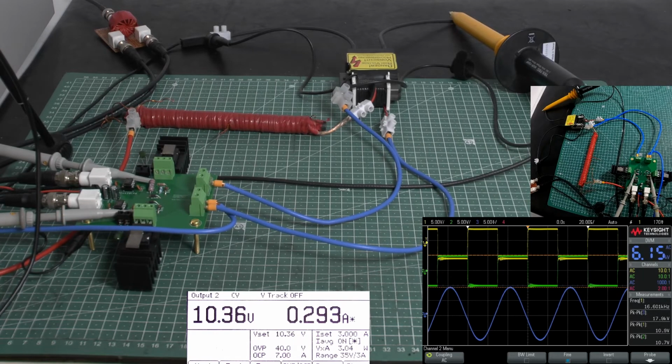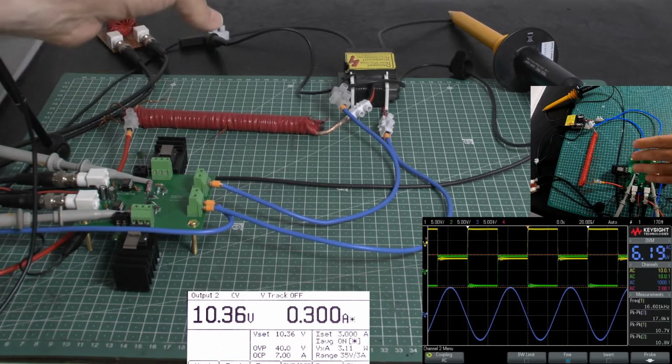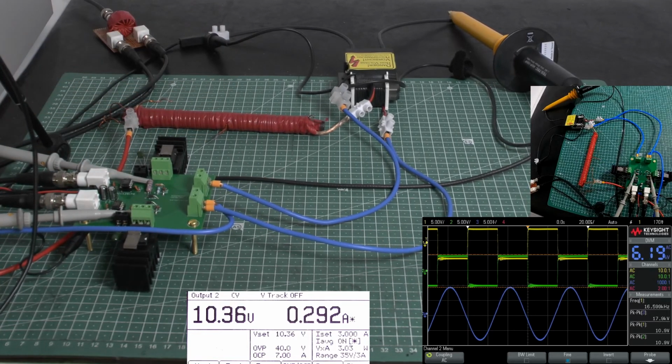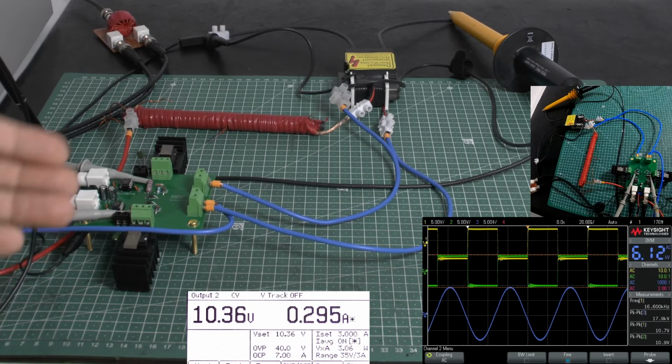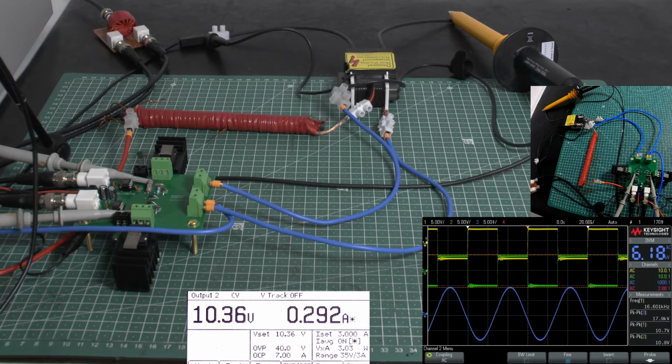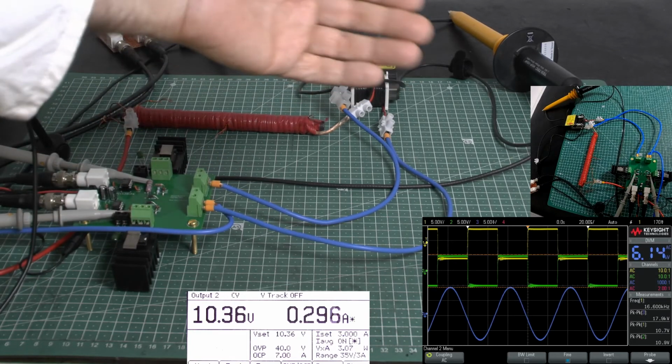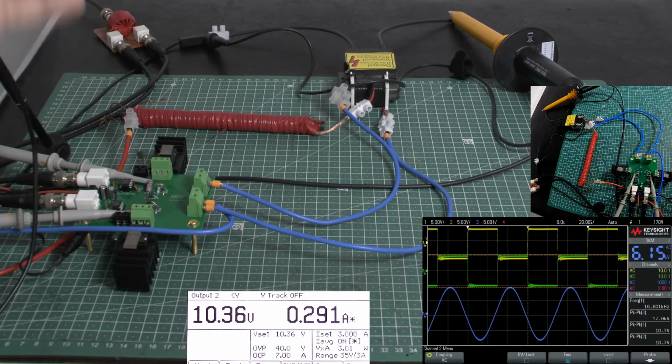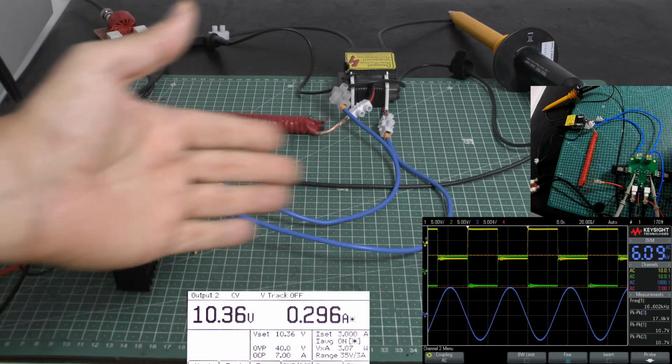This is the lowest value we currently have available, and that does clearly prove that the dual Class C with zero voltage switching is far superior to one Class C. Yes, we know we have 50% losses technically, because it works only 50% of the time. However, it is not really true, because the wave coming back from the initial push from the amplifier is also energy which is put in.